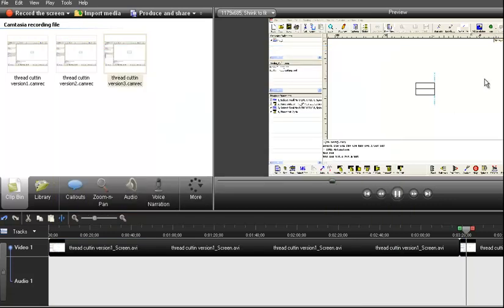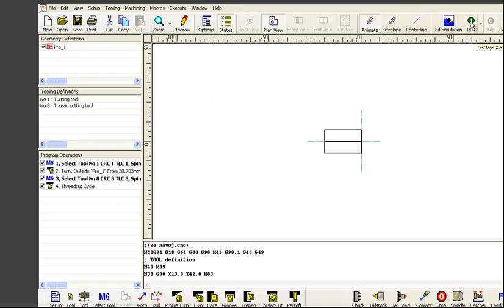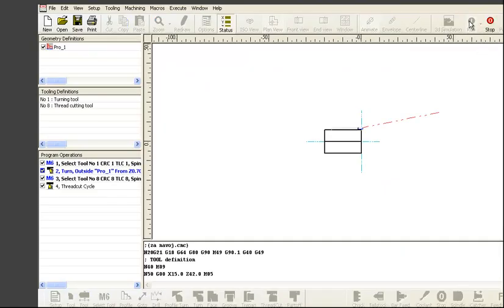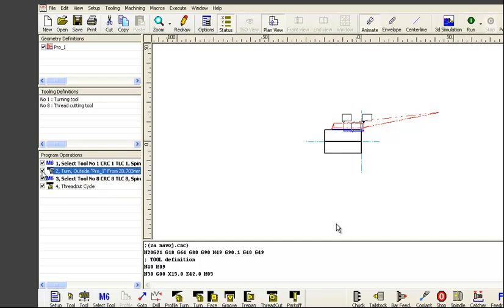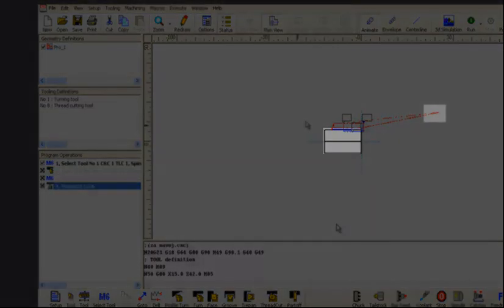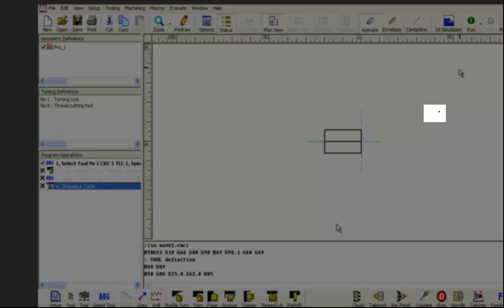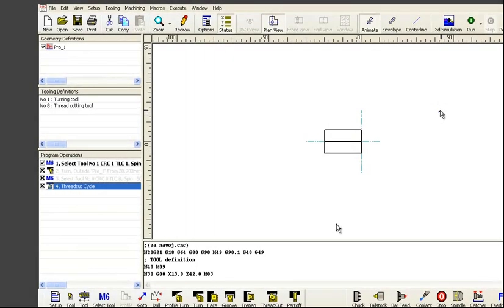So second approach with given post processor is shown here. So on left, on program operations, it is possible to see I did not use Go 2 operation, but I defined safe home position much further from my part that I machine. And this little triangle is my position.